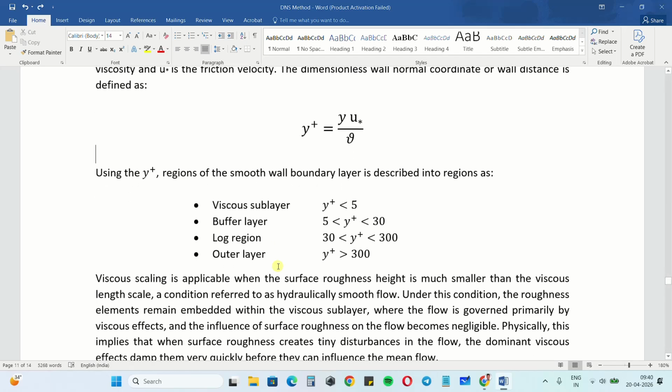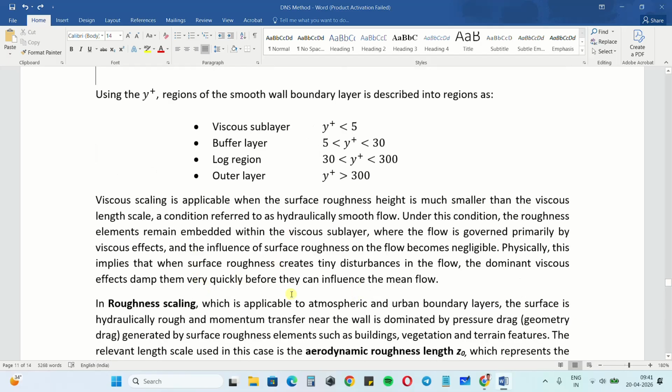So in order to approximate the actual near wall flow behavior, we have to have the right y plus value, okay, for the wall functions to better fit that approximation. Okay, so that's a situation where you technically call it hydraulically smooth case, where the roughness has minimal effects.